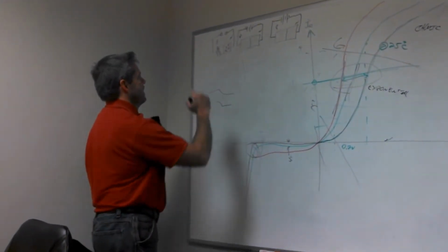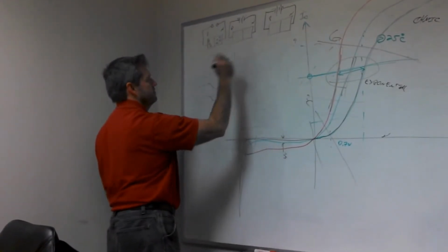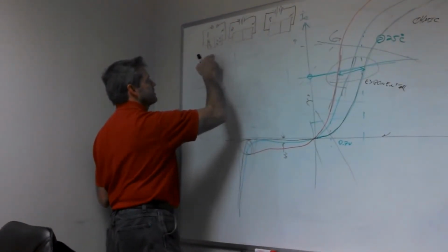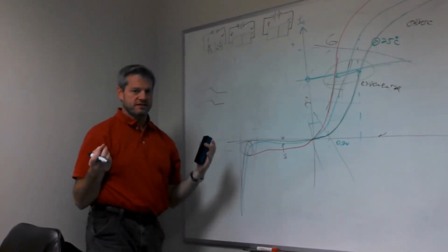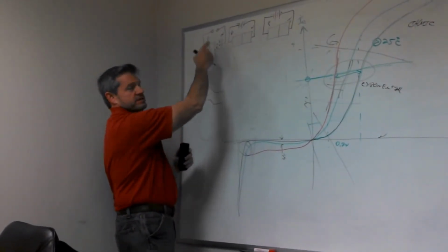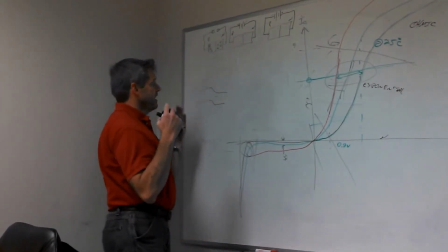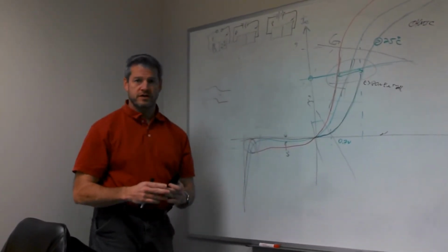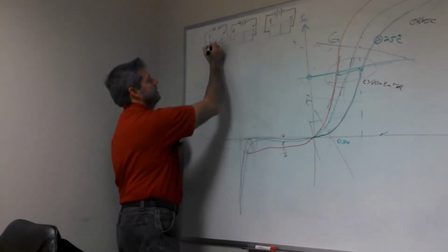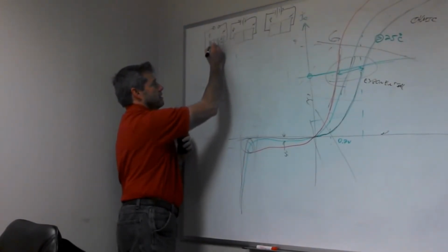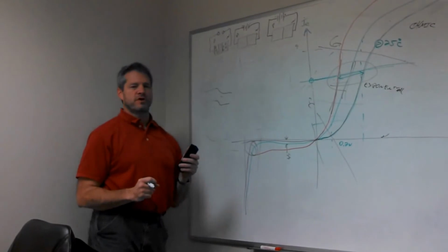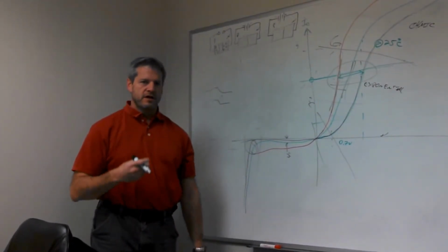And nothing flows. Now, from a point of view of what's going on in here, like I said, thermal energy excites these things. Electrons jump from this side to that side and recombine with holes and become effectively neutral. And there's what's called the diffusion length, which is part of carrier lifetime and some other things.